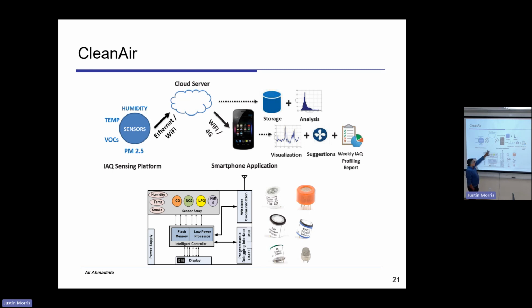The way it worked, it first did not send all the information directly to the cloud. It was sending to an app on the mobile phone. We used Bluetooth to send the information. And the amount of data here is very small, so it is not a huge amount of data that causes a huge delay. We also don't have a real-time constraint that you need to meet, for example, within a millisecond. Even a second of delay here doesn't make much difference, because it's humidity, and we're not expecting it to change very much or very fast.